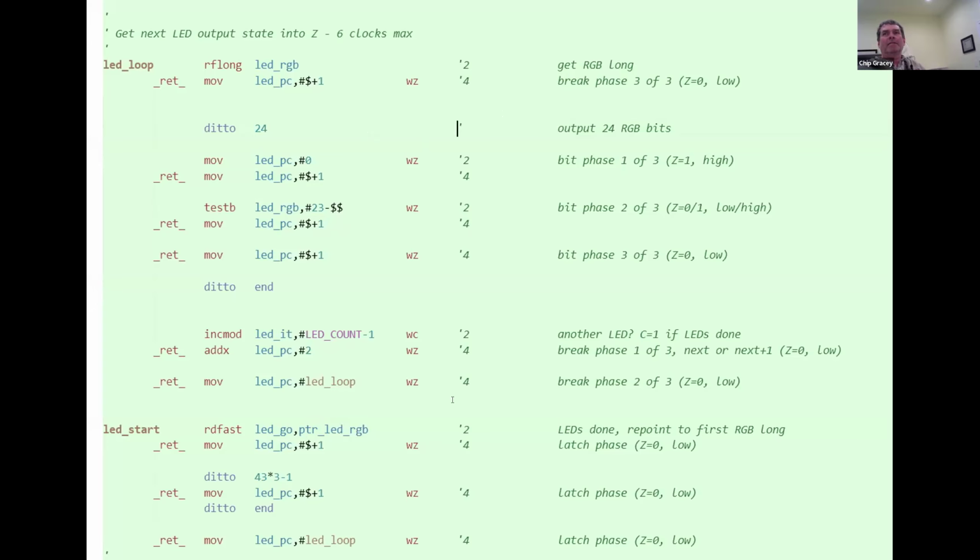It solves the problem of how to marry two dissimilar state machines by keeping the resolution of one super simplistic. You just call it when you want the next state, and then you use the middle state twice. Because I needed a bigger gap in order to operate the latch, because that's an exceptional timing thing, which happens only when you've run all the data through the serial chain.